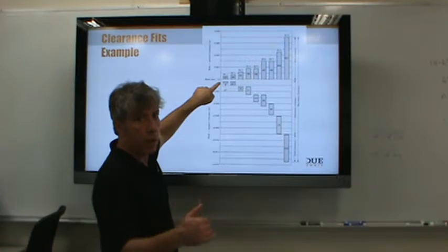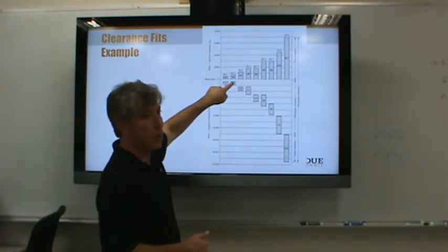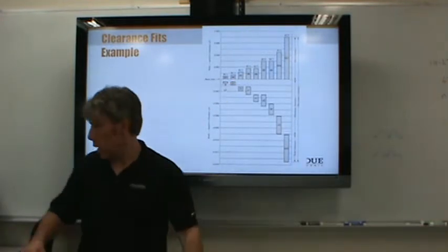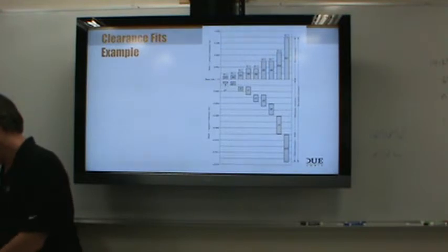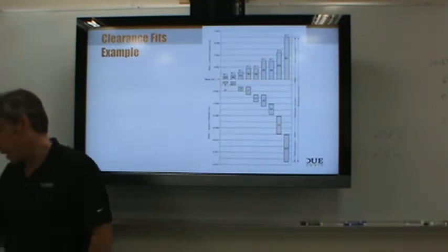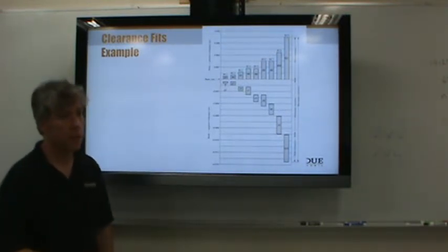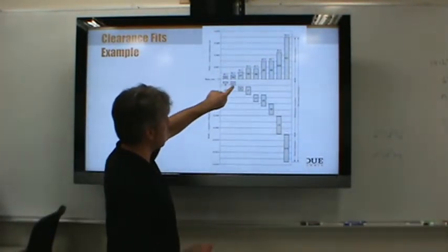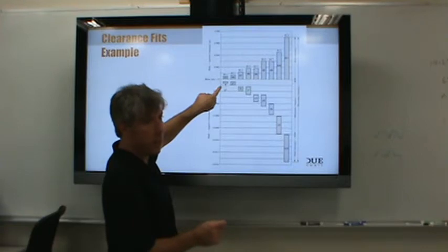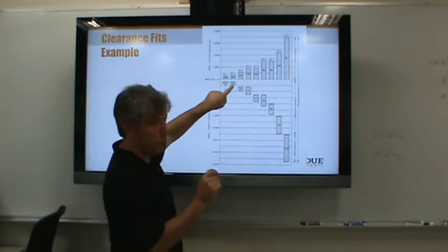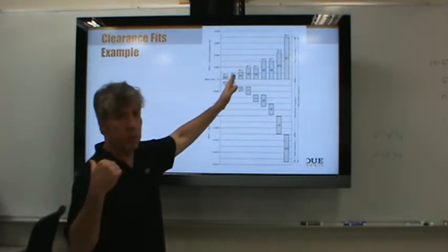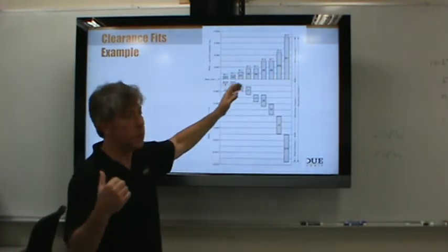We're going back to the shaft now. How much? No, this is 0.4. Okay, so if you look at the shaft, the numbers you see there are negative 0.4 to negative 0.9. See that? So this point is negative 0.4. This is not quite negative 1 thousandth. This is negative 0.9 thousandths. Okay? You understand how this relates to what's in the book, what's in the table?